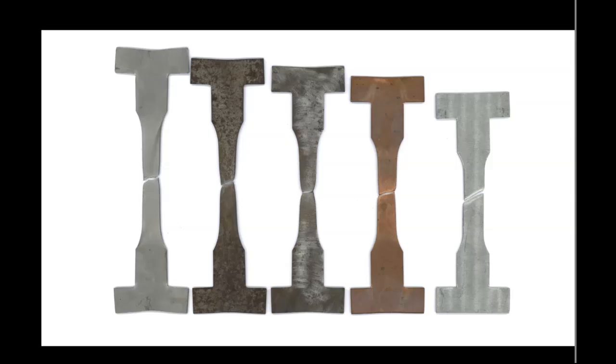So what this question really asks is that you've got 2 samples. One sample displayed larger percentage elongation, longitudinal, and that sample would also display larger reduction in percentage of cross-sectional area. That was a ductile sample. Another sample would have smaller values for percentage of elongation, so it would not elongate as much, and also it would not shrink as much.